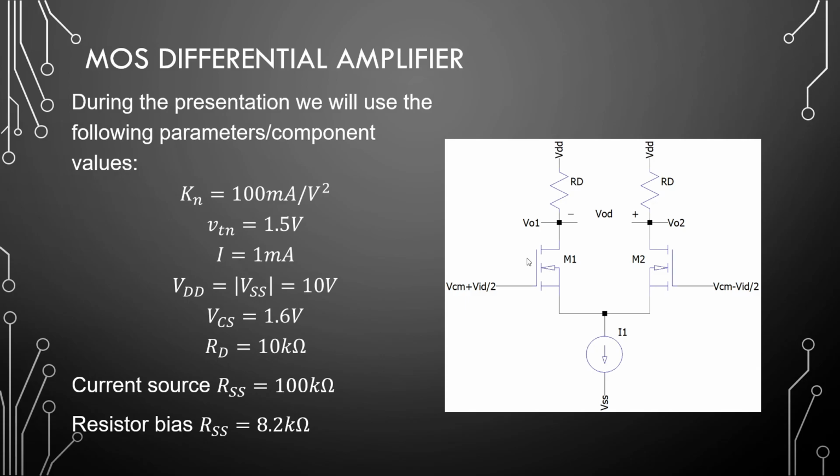So before we start the analysis, in a previous video we spoke about common mode and differential mode. So when we're doing common mode signals, we will be putting it in on both inputs, and when we're doing differential, it will either be the full signal on one half of a circuit or a non-inverted and the inverted version of a signal distributed between the two inputs.